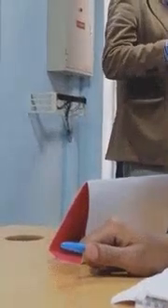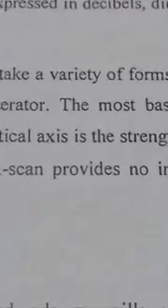The vertical axis is the strength of the return, and the horizontal axis is the time delay or range. It was giving you the distance the signal is from where you are. So you have got the radar rotating, and depending on how far the signal is, it will give you the distance. And it was calibrated such that when the scan is on the north, it refreshes. Every time the aerial passes the north, it refreshes on your screen.